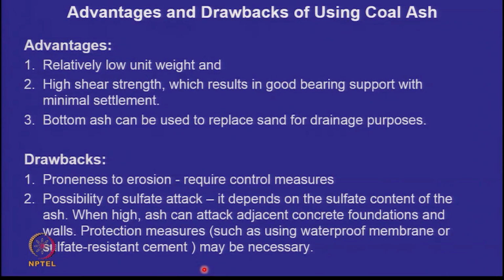So let us look at coal ash. The advantage of coal ash is that it has relatively low unit weight, it has high shear strength like granular material, which results in good bearing capacity as well as minimal settlements and other performance, reasonable slope stability, and good behavior of reinforced earth walls in such materials.